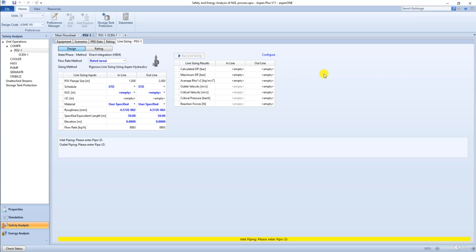Here again we have to play tricks such that the selected nominal diameter does not end up with an undesired result. Specifically, at a very low nominal diameter value, we violate the pressure drop limitation on both inlet and outlet side of the PSV. So my advice to you, start simple and grow up in size until you get the green strip.